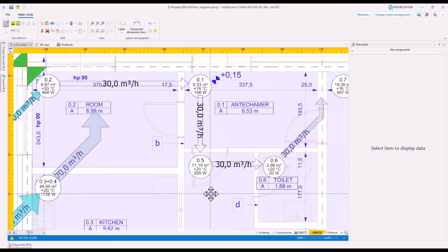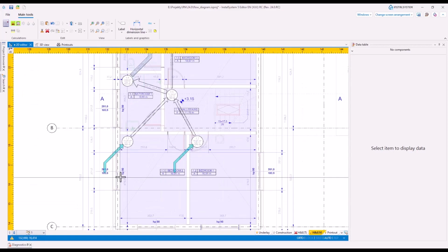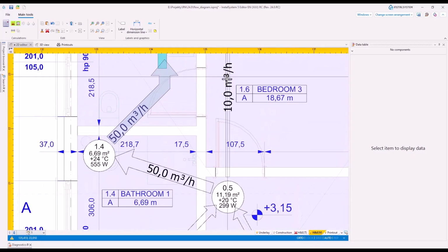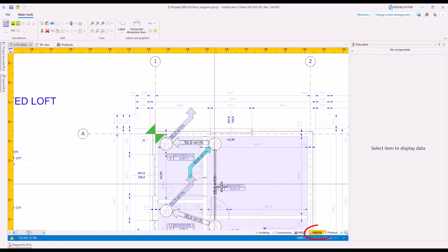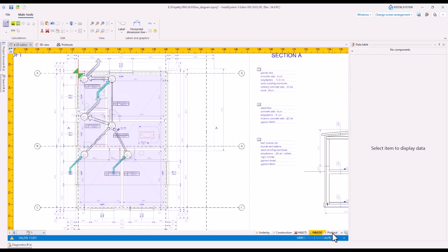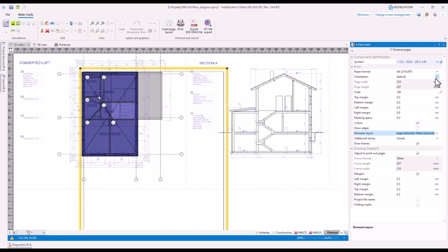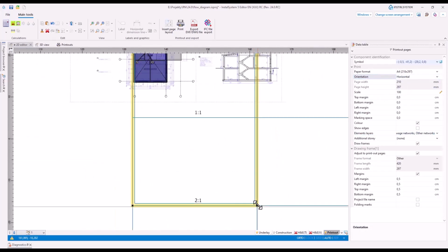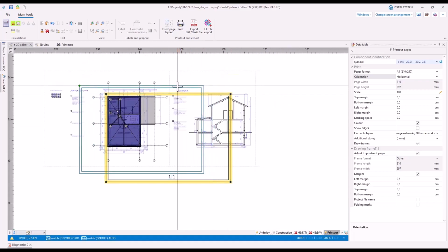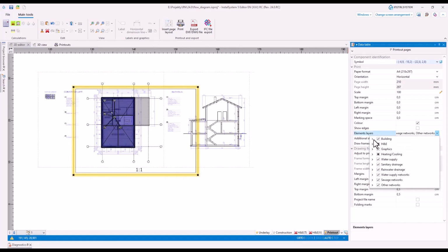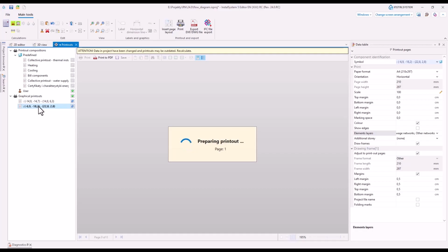After proper definition of ventilation airflows, grouping of rooms within building units and performing thermal calculations, you can analyze the ventilation airflow on plans in the special heat and energy editing scope dedicated for this purpose. This diagram with the values of ventilation airflows can be printed or, for example, saved as a PDF.